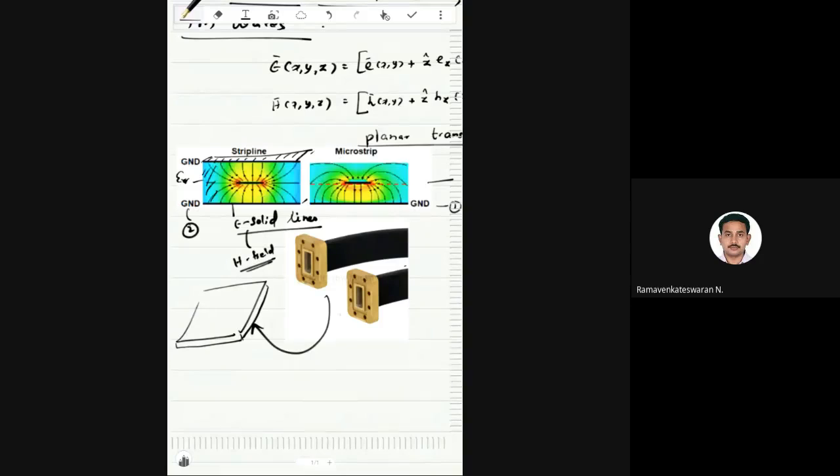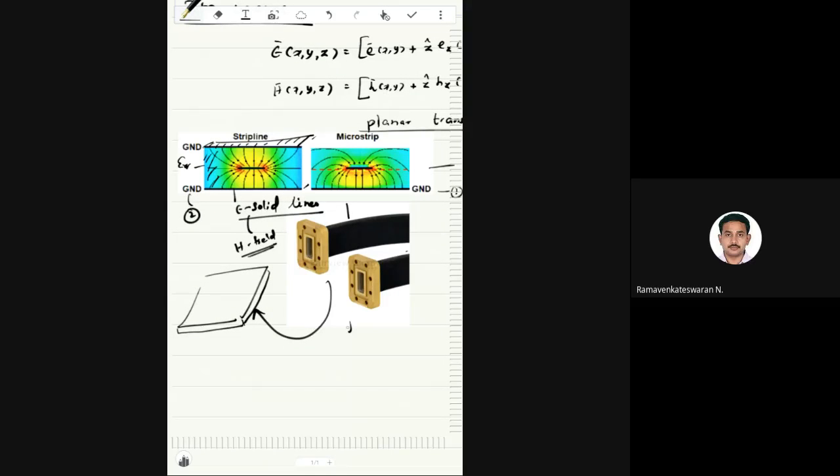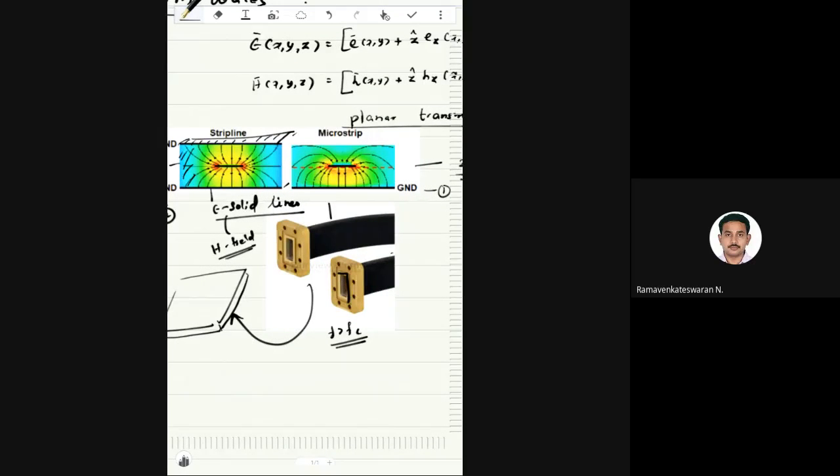Actually, the waveguide concept came into existence during the Second World War, around 1941. You can read a one-page brief history. Earlier, they proved mathematically that electromagnetic signals can propagate inside a tube. If it is propagating inside the tube, it has to meet certain criteria. The frequency has to be above the cutoff frequency, and the dimensions should be properly designed. If this is B and this is A, then A and B should be designed properly for a certain range of frequency. Definitely the cutoff is related to the dimension. That is 100%. They derived it mathematically.